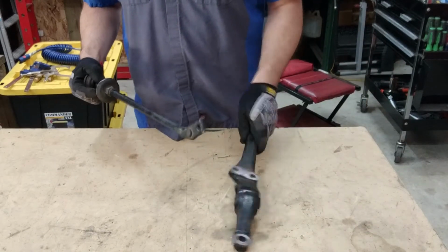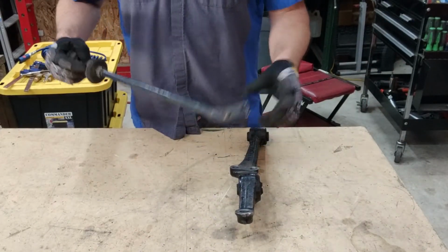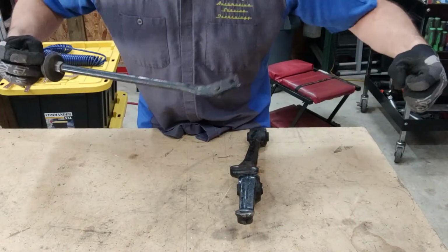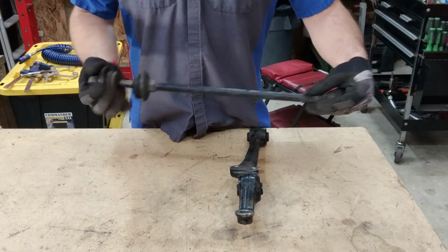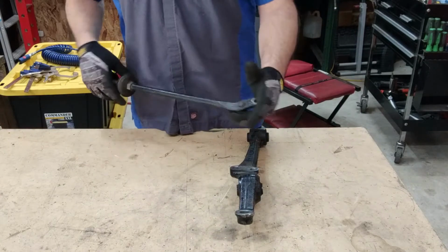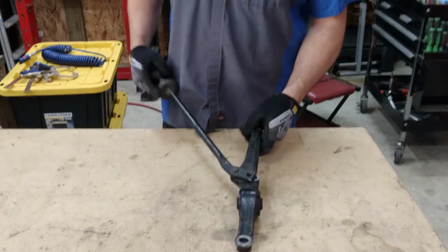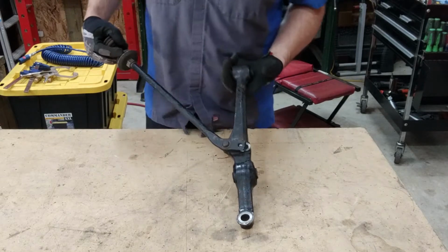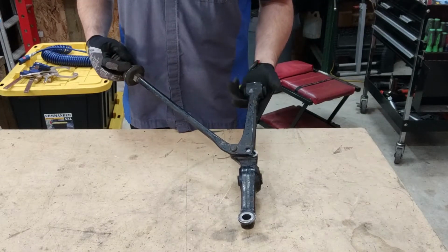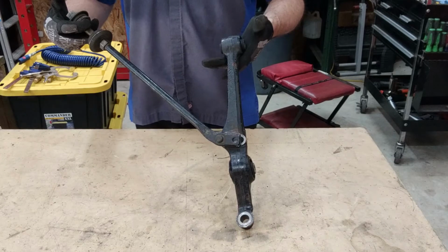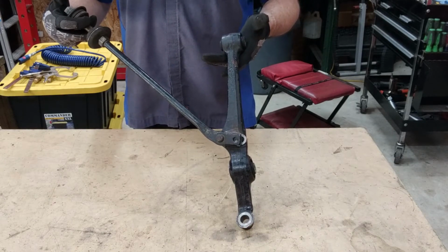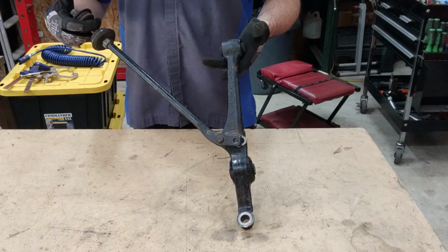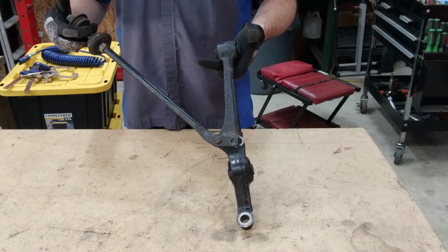Also, this bar is going to resist tension by doing the same thing in the opposite direction. So it is providing that fore and aft stability of the lower control arm if that lower control arm is only connected to the chassis at one location. This provides that triangulation, that strong geometric triangular shape that will stabilize the wheel on the suspension.